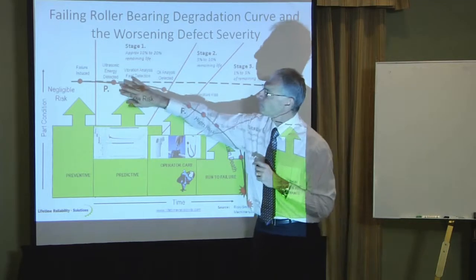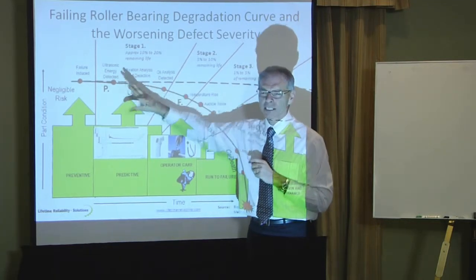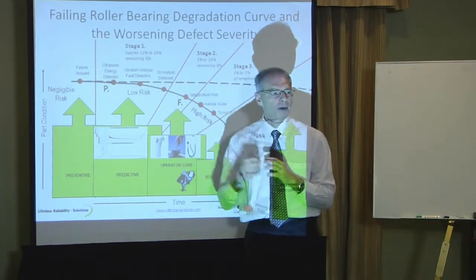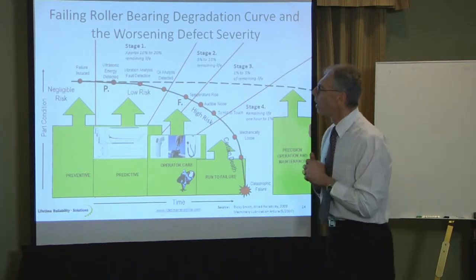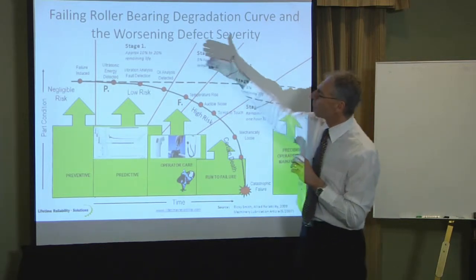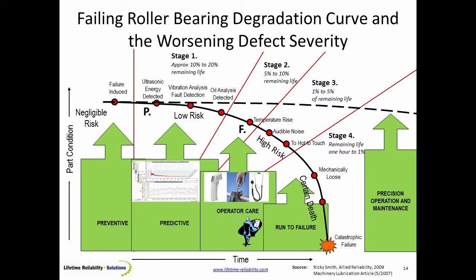That's the earliest point in its bearing life that we can detect some evidence of it no longer being in good condition. We do that with things like vibration analysis and ultrasonic energy detection. So we have some very high technology solutions here to find that point.